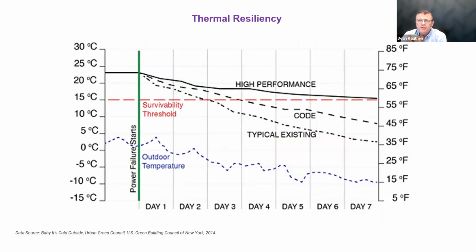And holistic approaches to design for thermal resilience also take into account the need for external shading devices to block excessive solar gains and provide effective natural ventilation to provide free cooling during heat waves. So thermal autonomy and thermal resistance are interrelated.